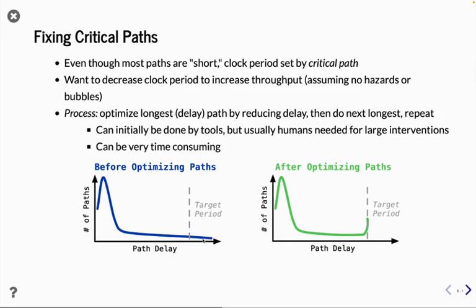And so normally this is a very time-consuming thing. This is where the time goes. I mentioned a second ago talking about your design in terms of FO4, what you're targeting. If you have a lax frequency target, hardware design is a lot easier than the very aggressive thing. If you want to run at a super, super low FO4, super high frequency, you spend a lot of time optimizing paths. But if you don't care and you want to run at 200 megahertz on a brand new process, hardware design is not as hard. You can do things a lot easier.